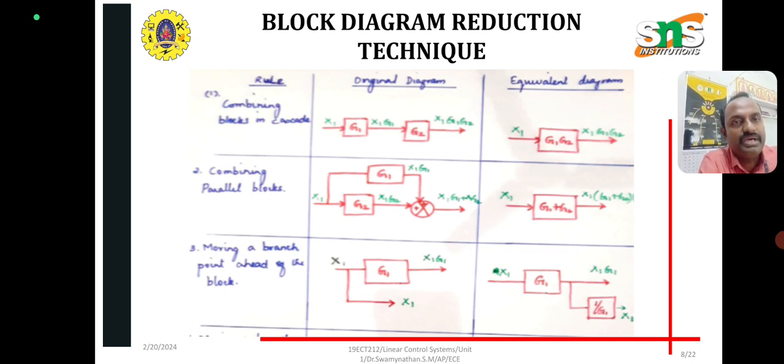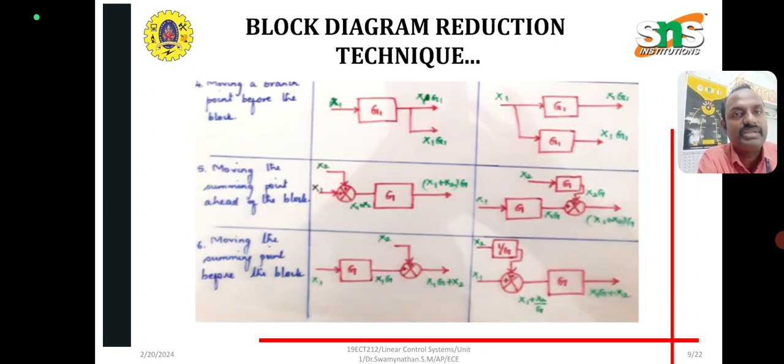Next, two, combining parallel blocks. G1, G2: how can you say it is parallel? Both ends are connected with each other. So parallel means G1 plus G2 is the equivalent diagram. Rule 3, moving a branch ahead: moving past G1 to the other side means 1 by G1, that is G1 into 1 by G1, that is the equivalent diagram. And rule 4, moving a branch point before the block. Before means G1, after means 1 by G1.